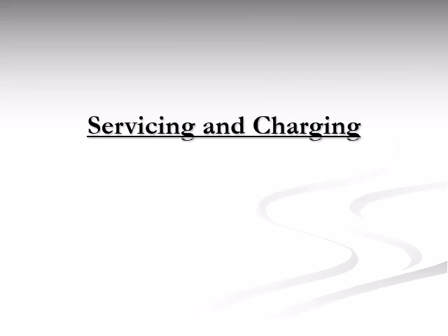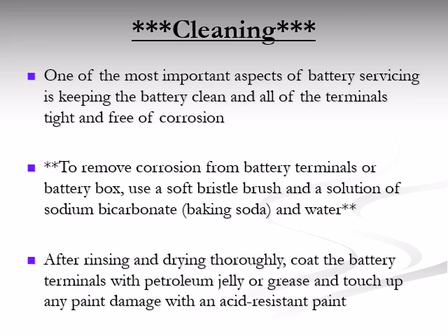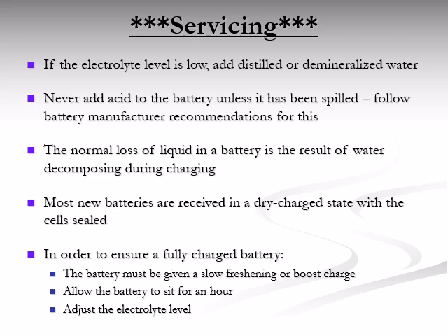Now let's focus on servicing and charging the battery, starting with cleaning. Keep batteries clean and terminals tight. Use a baking soda solution to neutralize corrosion, rinse thoroughly, and protect terminals with grease. In servicing the battery, add only distilled water, not acid, when electrolyte is low. Most new batteries need a slow boost charge before use and electrolyte adjustment afterward.